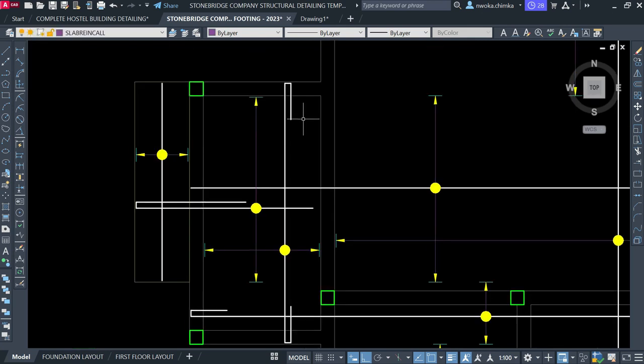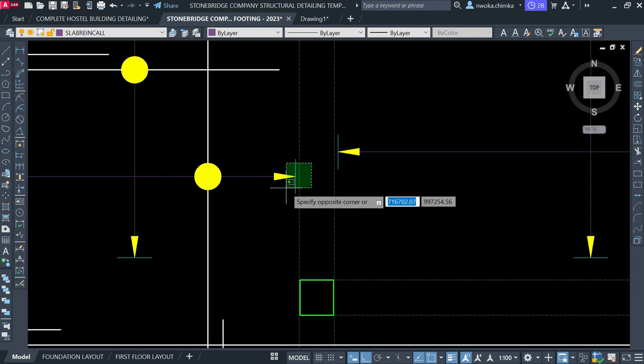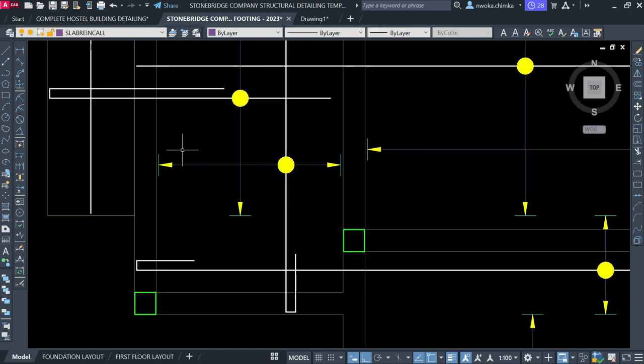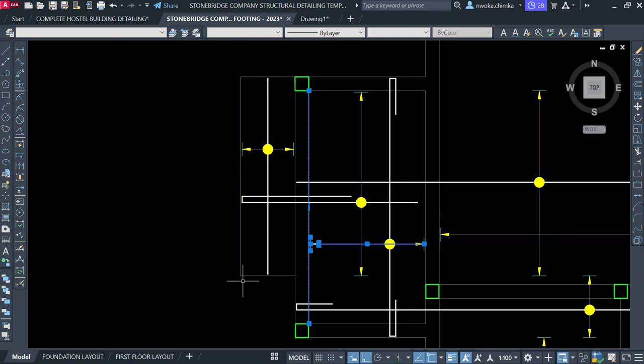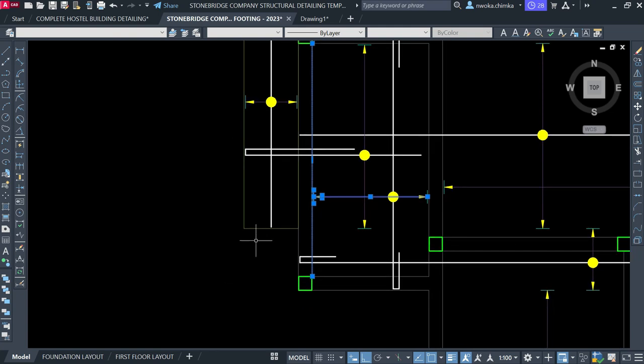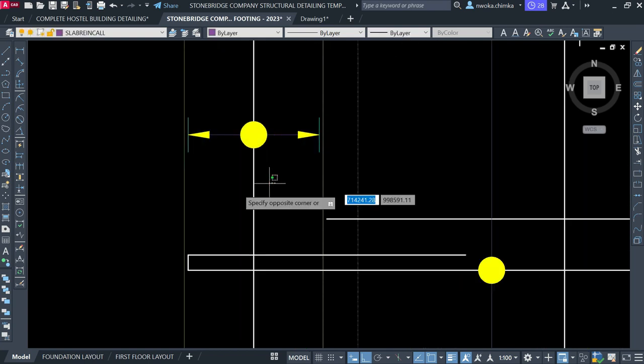Now another bar continues, which will fit into this panel, continuous bend and bend, and then runs from this very point here to this very point, and now stops because there's a change of shape of the cantilever, which is here. This place doesn't have anything, so the bar has to stop here, and then this bar continues.